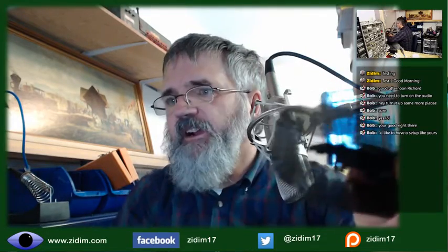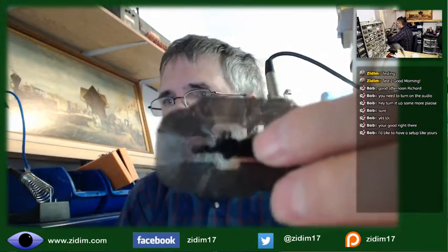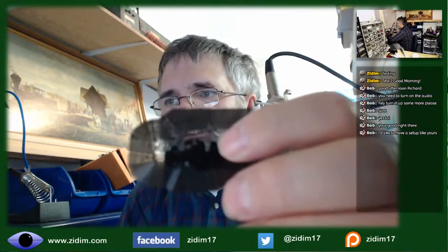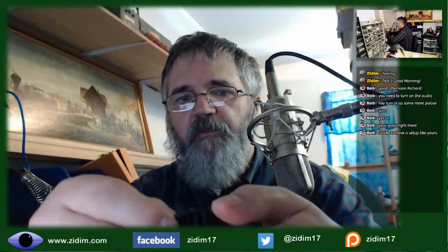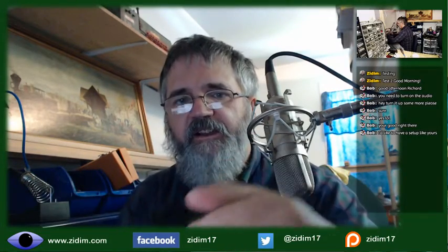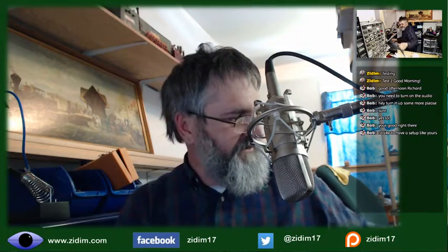I had a brim, but where the supports are, you can see right through there. Minimal support, so the brim didn't do any good. And it broke off the print bed when we got that height. I can see the base of the horse, but that's it.